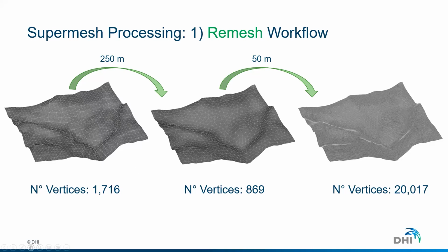So you see this surface, which is a topographical surface, which I'm going to use for the demonstration exercise later. I could keep calling this remesh operation or retriangulation in FEFLOW to end up with a more refined surface. It will clean up some of the problems that I have and would also add a higher degree of detail.